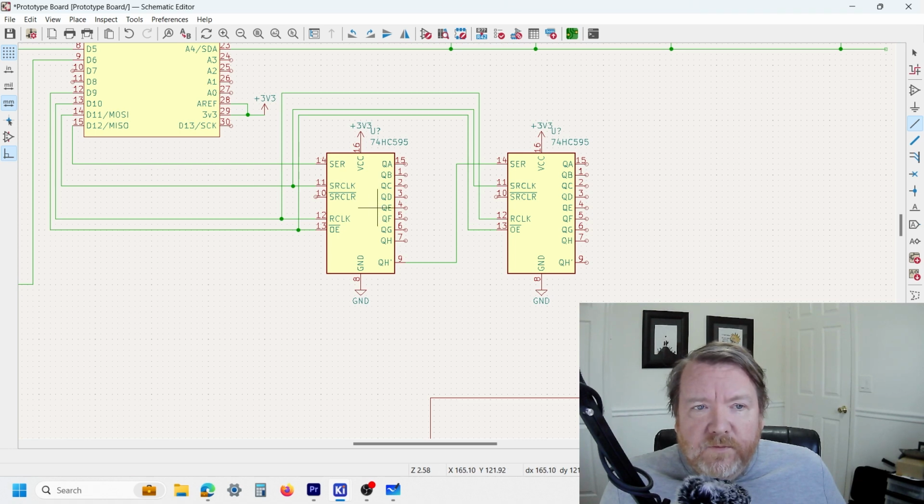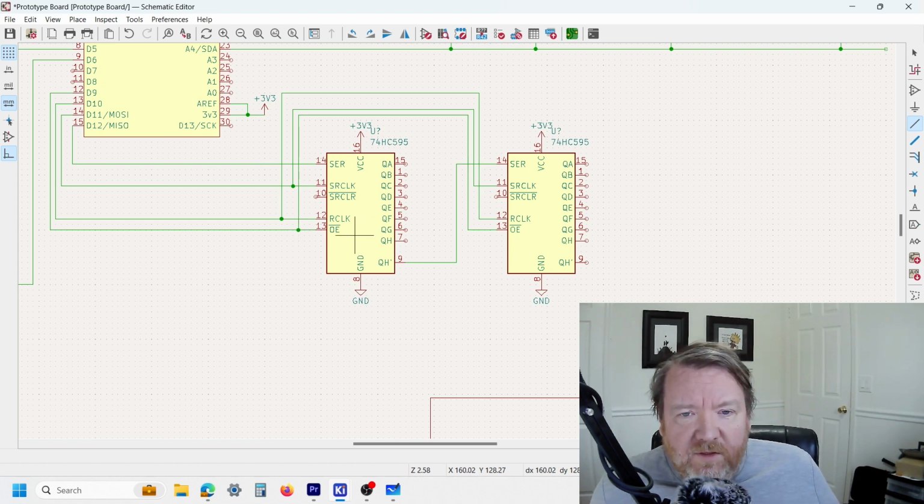So now, again, with the few output pins, you don't even need to have the output enabled. If you're going to be using this all of the time, then you can just leave that enabled and free up another one of the pins from the digital I/O.